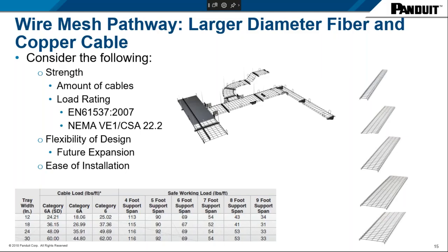When you're considering which wire mesh pathway you should go with, you want to consider the strength of the basket itself. You want to consider the amount of cables, the load ratings, and the flexibility of the design. How easy is it going to be for me to expand in the future? Part of this, as you're looking at a wire mesh design, is the ease of installation. We understand that contractors and installers are installing this on top of ladders. We want to minimize as much as possible the labor that's involved when installing these baskets.